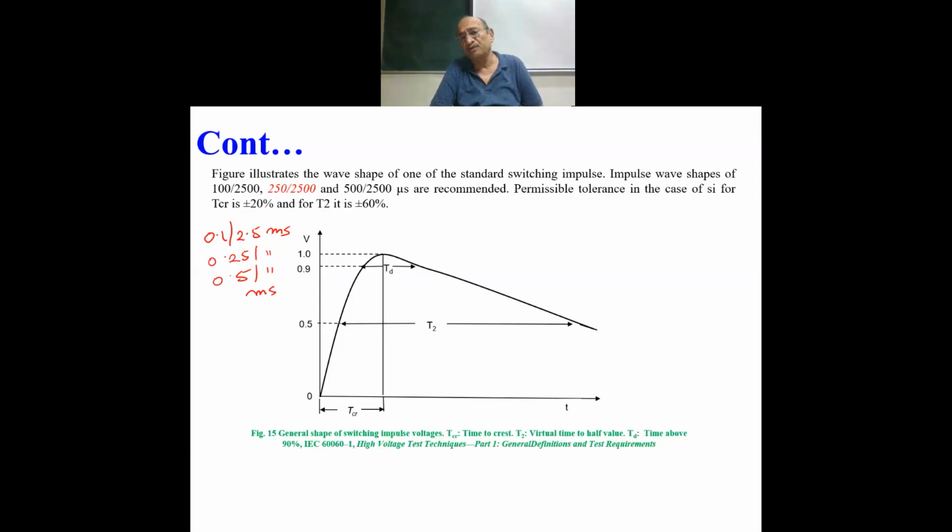So when you go to such a high level of transmission lines, the significance of lightning impulse voltage is not so much there. The significance of switching impulse voltage increases. We have been talking about it. The reason: the highest known lightning impulse voltage produced on the transmission lines, the insulation level at 400 kV and above, is able to take care of the maximum lightning impulse voltage magnitude.